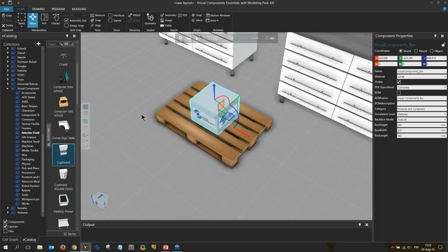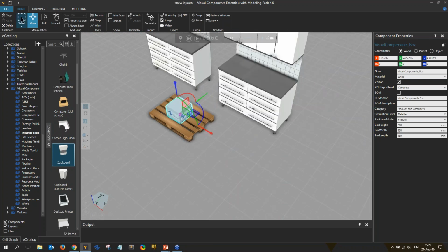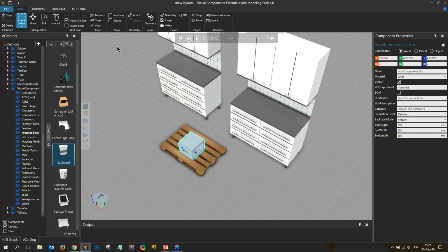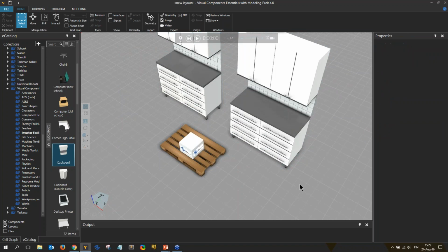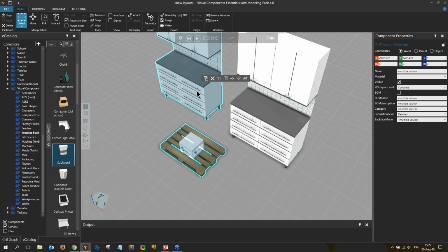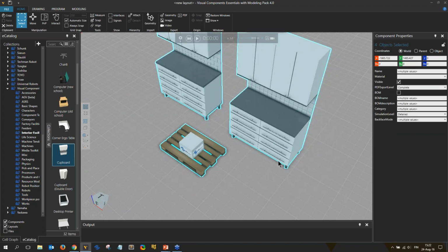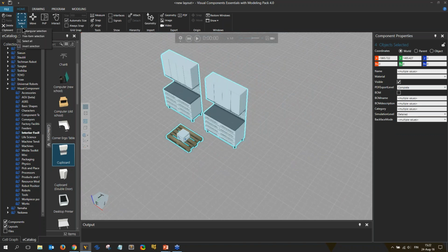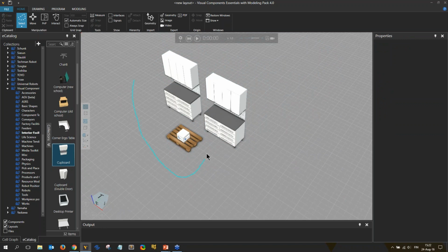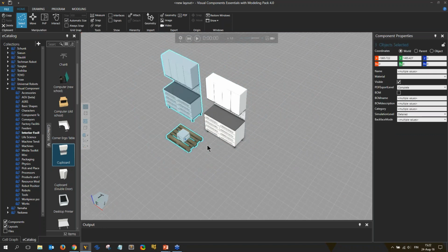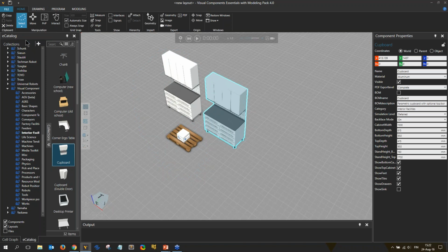and before going there, let's take a quick look at the select tool. So we already saw the PNP and move tool. Now if we go to the select tool, that allows us to do selection like this. You can do multi-selection also by holding down Control and adding stuff to your selection or removing things from the selection. But with the select tool you can draw a rectangle to do a box selection. You can also have this freeform selection, where you can draw in more detail what you want to include and exclude. Then you can invert the selection or simply select all.